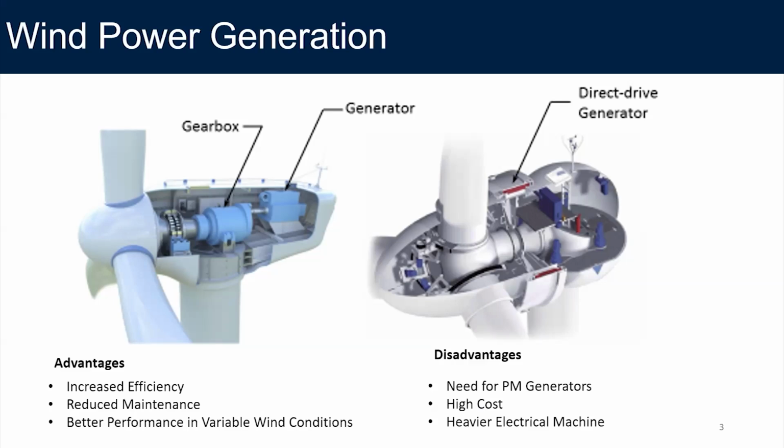The magnets are high density, the density is the same as iron, and because you need a huge volume of magnet for high power permanent magnet machines, the overall weight of the generator is probably equal or more than the geared generator option, the package of the gear and the machine itself. So that's one of the disadvantages.